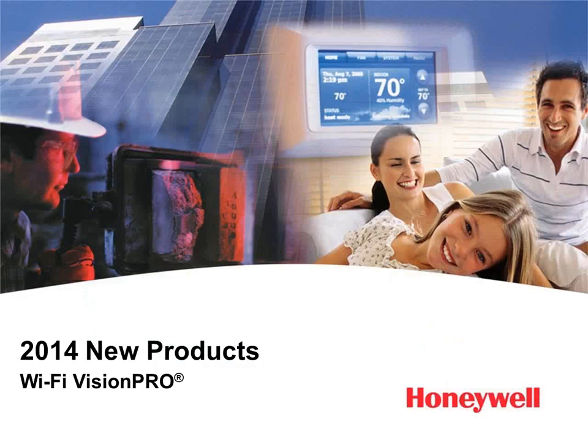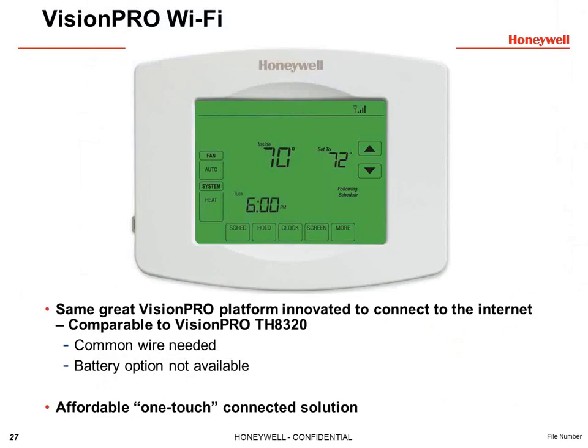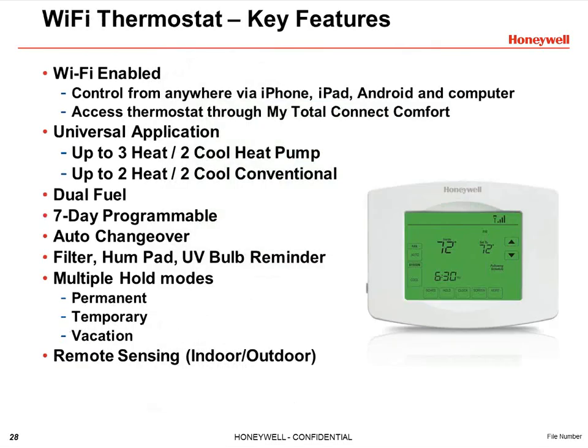As we go into more Wi-Fi products, the next step up is going to be the Vision Pro. So if we're talking about the Focus Pro, which is push buttons, now we're talking about Vision Pro, which is a touch screen thermostat. And again, remember, you need 5 wires on the Wi-Fi thermostats. Or you can use an add-a-wire, which we'll get to.